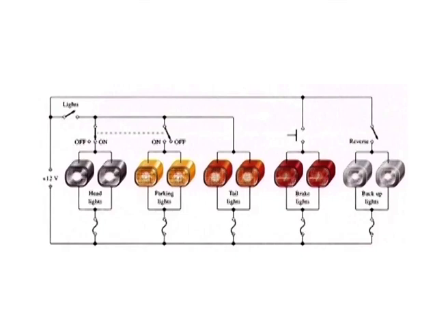When one headlight on a car goes out, it does not cause the other lights to go out because they are all in parallel. Notice that the brake lights are switched on independently of the headlights and tail lights. They come on only when the driver closes the brake light switch by depressing the brake pedal.